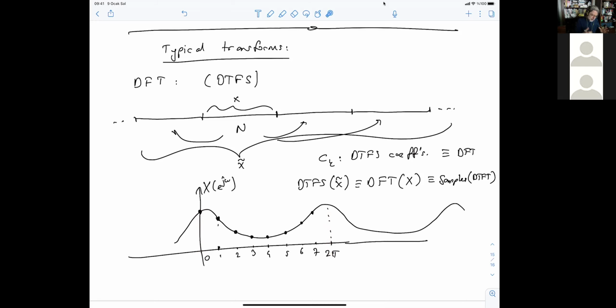So as you see, the more DFT samples you get, the better continuation or approximation that you have for the discrete time Fourier transform. So if anyone asks you to plot the discrete time Fourier transform, this X of e to the j omega, you should try to obtain the DFT using FFT in MATLAB, for example, with as many points as possible.